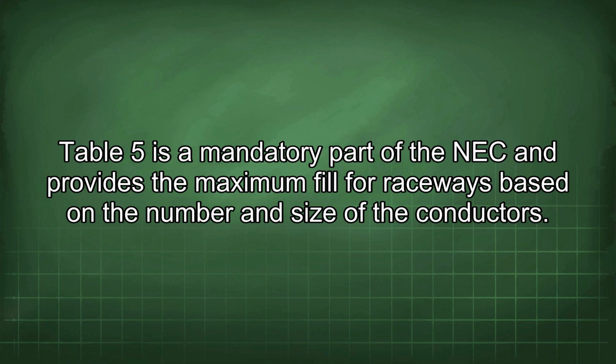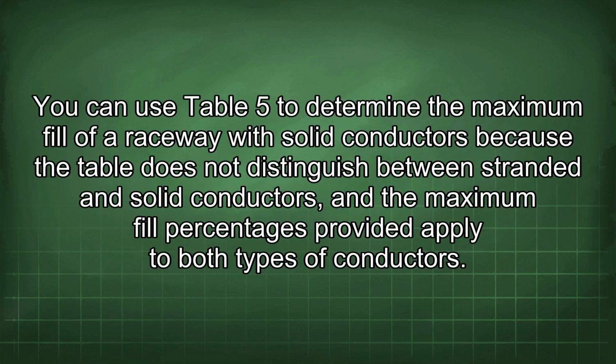based on the number and size of the conductors. You can use Table 5 to determine the maximum fill of a raceway with solid conductors because the table does not distinguish between stranded and solid conductors, and the maximum fill percentages provided apply to both types of conductors.